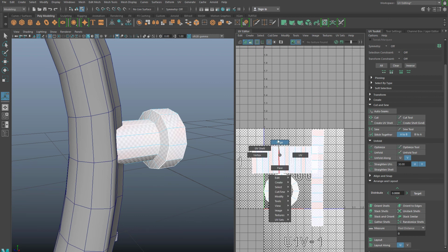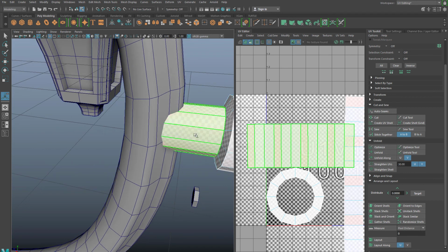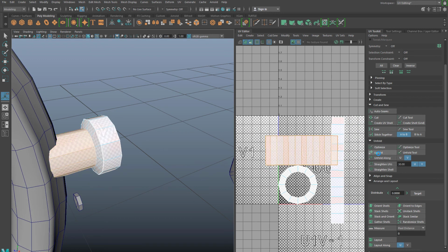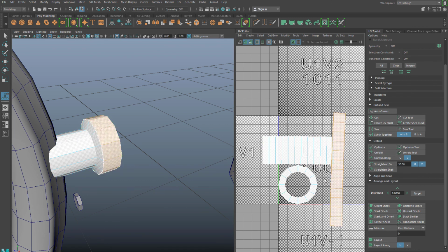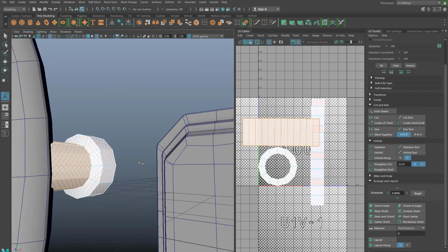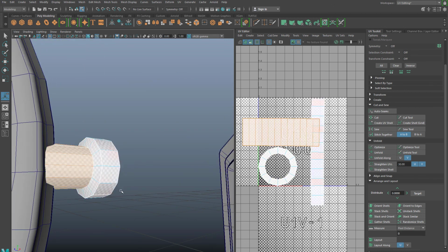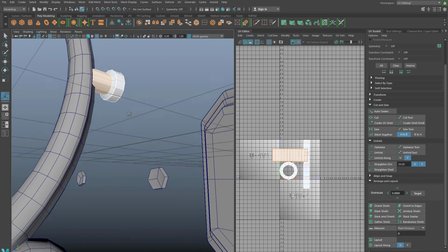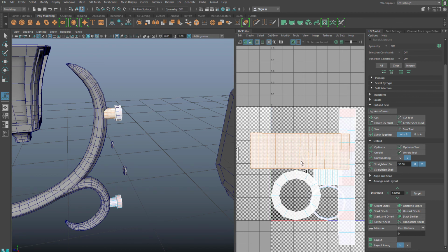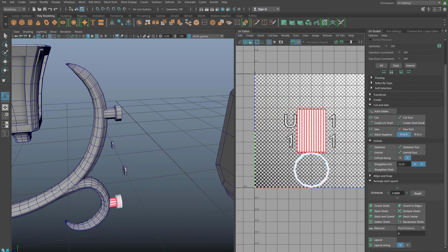those edges. So all I did was take the UV shell that was automatically mapped and it just broke it up in chunks, and I mean I can still unfold it, but as a general thing it just chunked it, and then I just identified each edge that was broken up into sections and then just stitched those together, and that will create a pretty dang good UV layout for that shape. So same thing on this one.